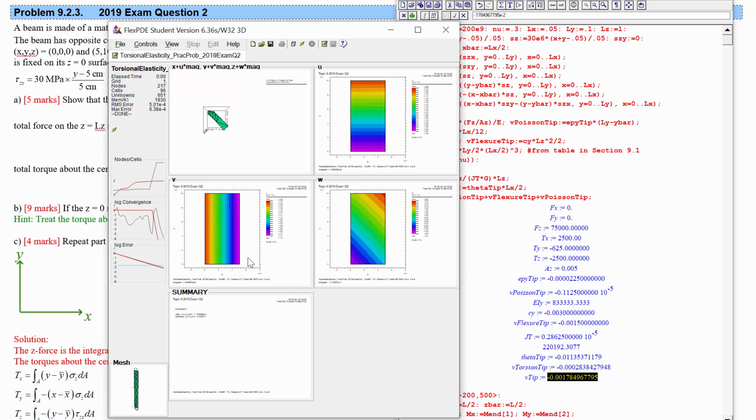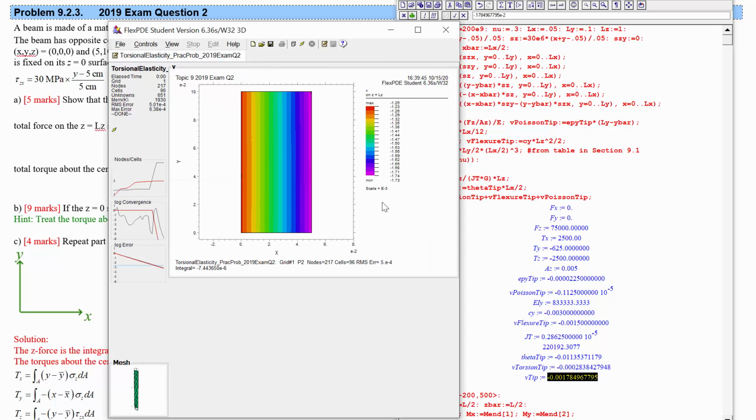So on this surface, we can see how the Y displacement depends on position. It mostly doesn't, which is consistent with the displacement being almost entirely, well, okay, so the bending would have us not change it at all, but what is this difference from here? This is from the torsion. So this change in Y at different positions, giving us a more negative Y, the more positive X we go to, is from the twisting.